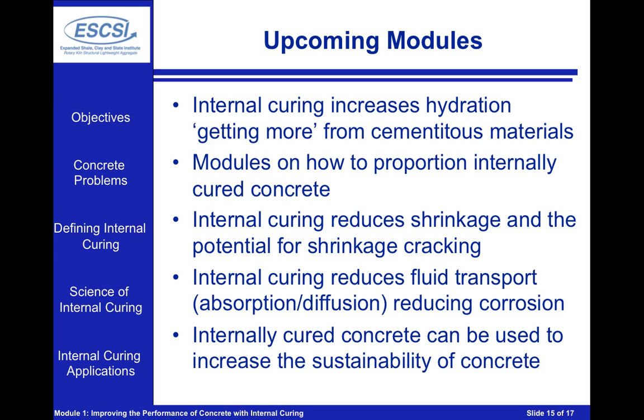This is really one of the main aspects of internal curing that's beneficial, and what we're going to see is that this works better as we start to use more supplementary materials. This works better as we go to higher performance concretes. So we really have a solution here that can solve one of the real Achilles heels of these high performance concretes, and that's their crack susceptibility.